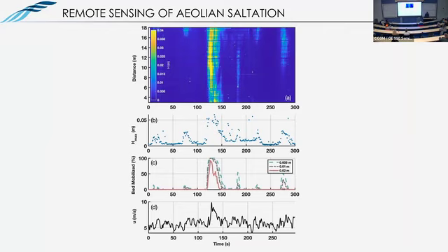If we take another picture of this, we can make a p-color plot on all of these panels. The x-axis is time, and on the colored panel is distance. This is the exact same thing we saw in the video from earlier, and I just want you to notice there's a lot of blues, not a lot happening basically for the bulk of this time, but the yellow strip is that whole sediment transport field being mobilized. So now we have a time stack of what's happening in terms of a transport field. We can think about when sediment is being mobilized across the bed.